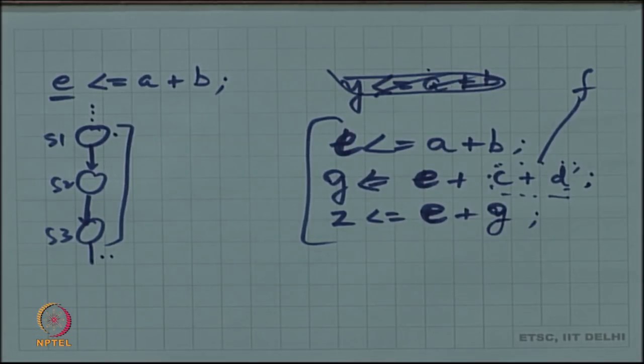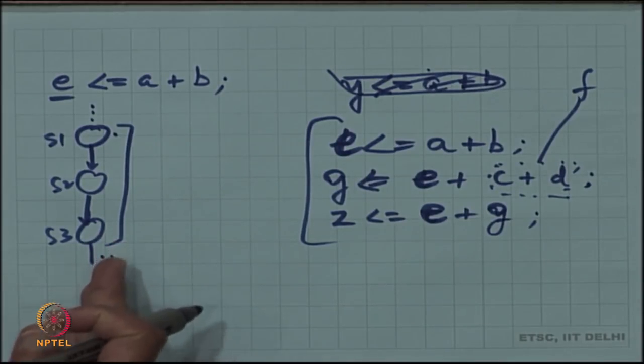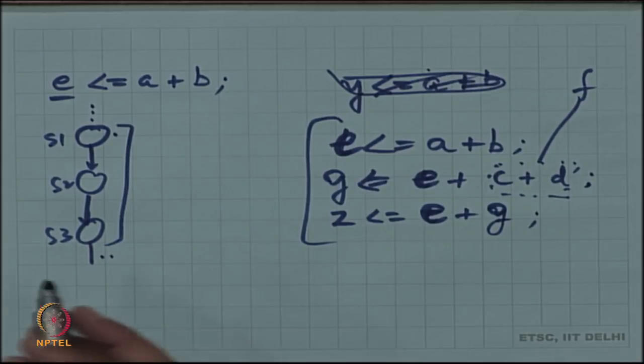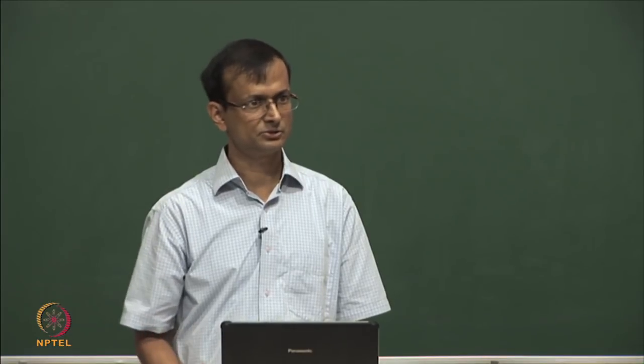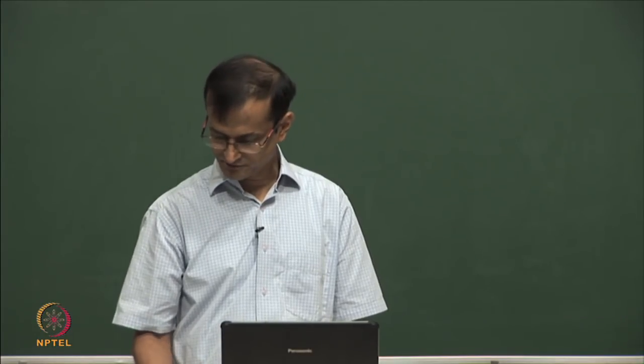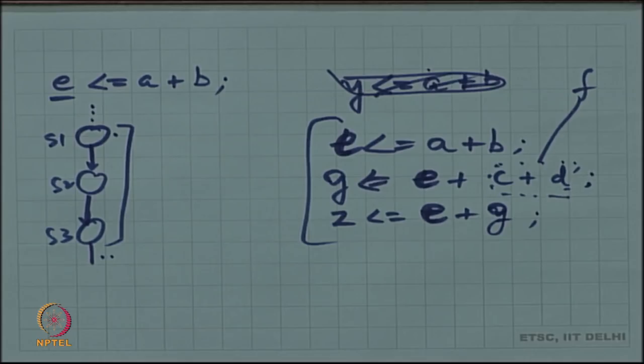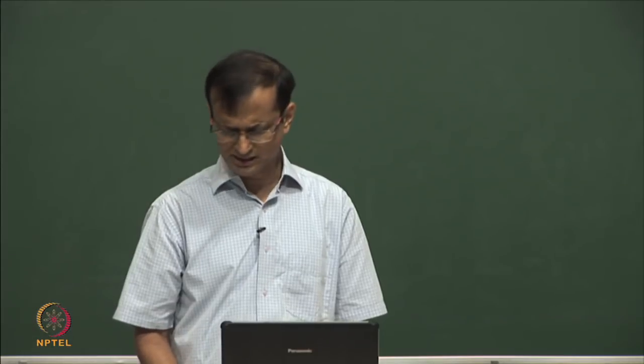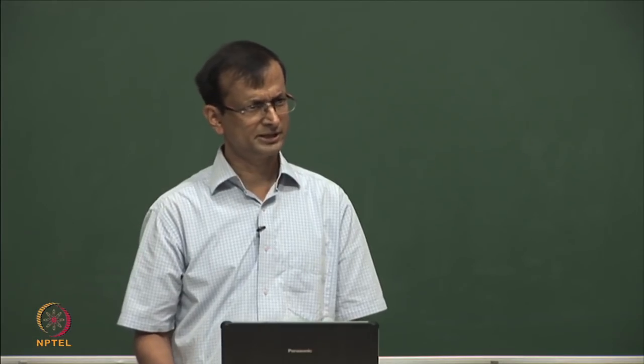Well, anyway, the FSM does not pick up the value. The values are probably going as the output and back into the input of some other component, it only sends the control signal. But if it is small, then the way to incorporate that in the FSM is to just have the right number of states, wait for the right number of states. You do not need an explicit counter there.